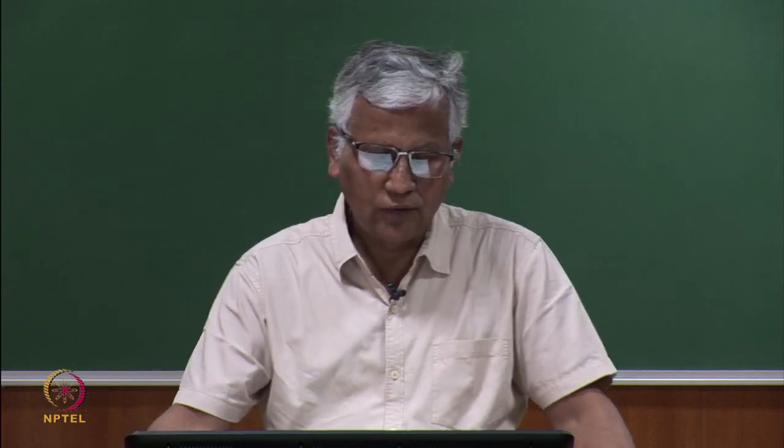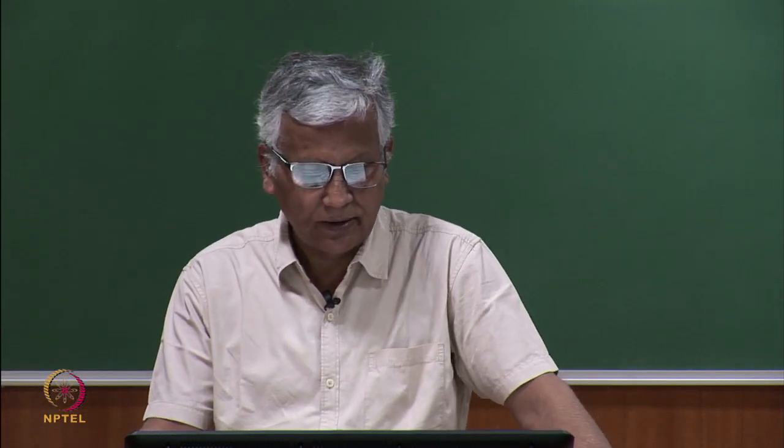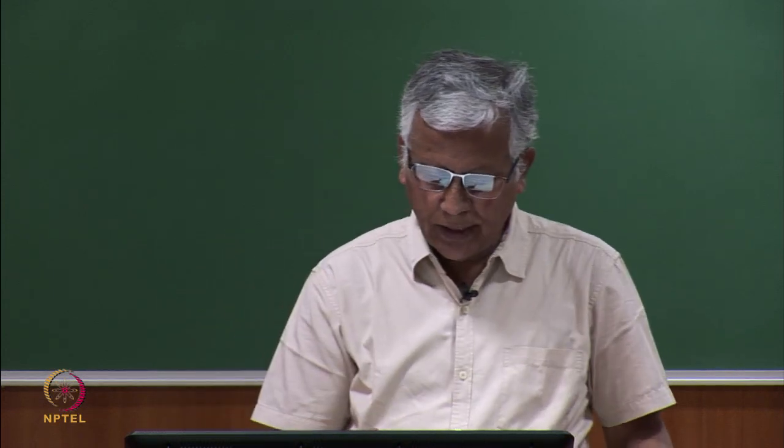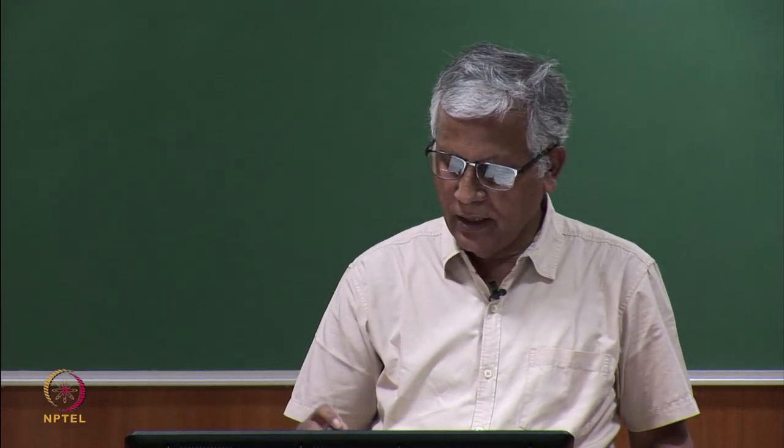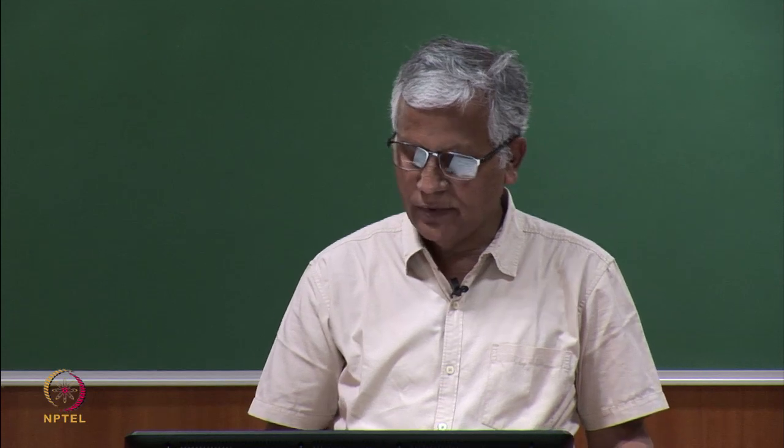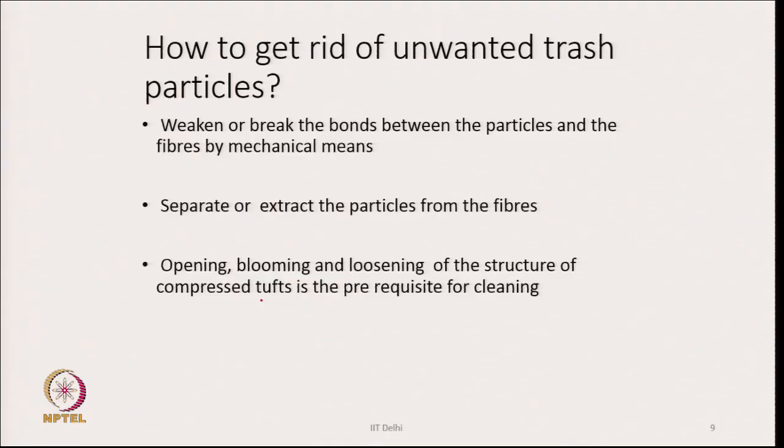Separate or extract the particles from the fibers. Once you have broken the bond between them, in a way they are liberated from the fibers. Now, we have to go for separation or extraction of the particles from the fiber. So, opening, blooming and loosening of the structure of compressed tufts is the prerequisite for cleaning.